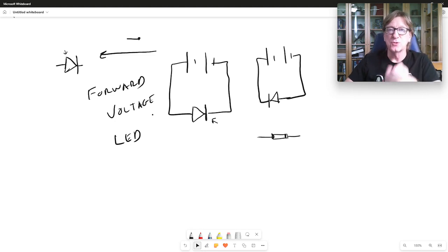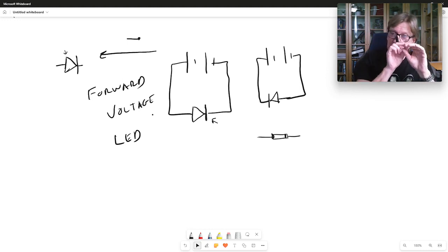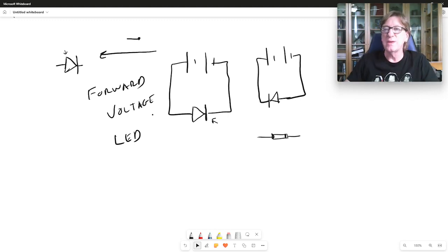When you point your remote control at a television, it's actually sending infrared light, and then there's an infrared receiver in your television that interprets the pattern of flashes to do what you want it to do. So that's a light emitting diode. It's just not light that you can see. So typically an LED, we mean one that's visible light in a certain color, and that has to do with what kind of energy drop we have. The different kinds of energy loss is going to correspond to different wavelengths, different energies of photons. So we can control the color of the LED by determining what that drop is when those holes get filled.